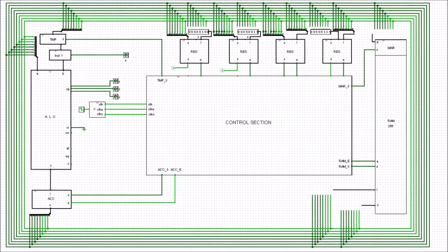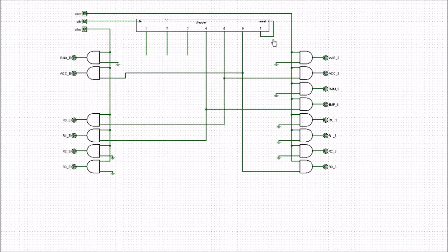So let's just finish this off here. If we were to go on to the next clock pulse, the set goes low. That means the information is now stored in this register here, and the whole thing goes low again. Now we go on and we went from point 6 to point 7, it went all the way back to 1 again, and now we're ready to start the whole process over again. So quite nifty, and it's best just seen via this example, and you can sit and mess about with this yourself, put different values into the registers and see what you can come up with.